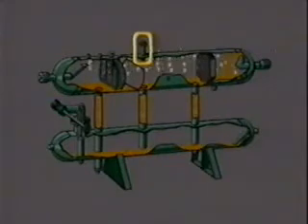In the upper tube, the gas separation section contains the inlet, baffles, straightening vanes, and mist extractor. On the very top, you'll see the relief valve or rupture disc. As the well stream enters the top tube through the inlet, the stream is deflected to change direction and velocity.